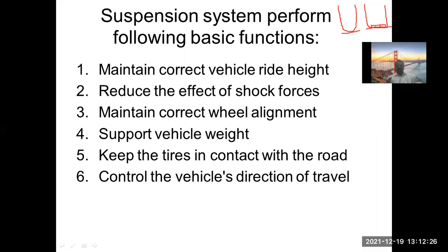Okay, if the side part of the tire is coming into contact, then this is going to wear very fast, because the tread area is going to have higher wear characteristics when compared to this, because the side walls are generally designed for flexibility. They are not designed for wear. Okay, and therefore that has to be taken into consideration.